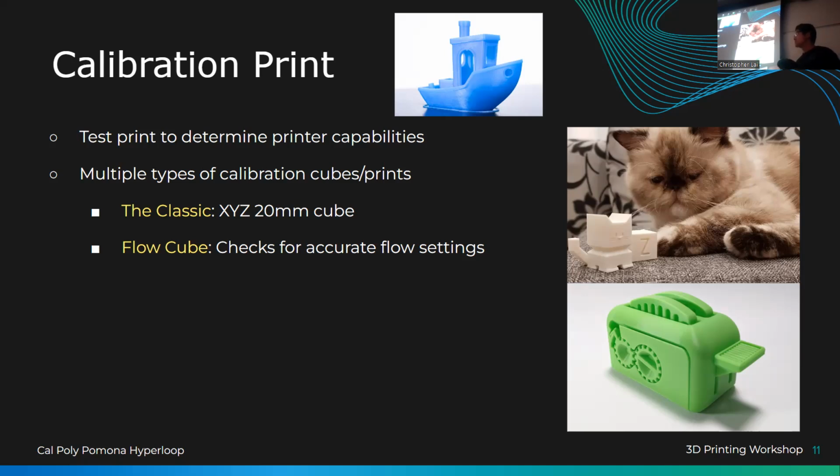If your extruder cannot keep up in terms of heating the plastic at an adequate speed while it's moving, think about it, if you're moving faster, you need to push more plastic per second. If your flow isn't high enough to do that, that's too bad. You're going to have skips, jams, all sorts of stuff. You can crash stuff, you'll destroy gears. So try to determine your flow.